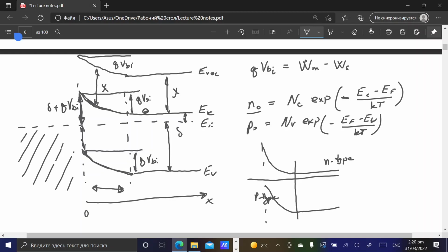And for its JV curve, the current-voltage characteristic, we will definitely spend time to do all the quantitative analysis of the current-voltage characteristic of a diode based on a PN junction. But here you can just believe me that the current-voltage characteristic of such a rectifying metal-semiconductor contact with a depletion region at the interface will look like this.